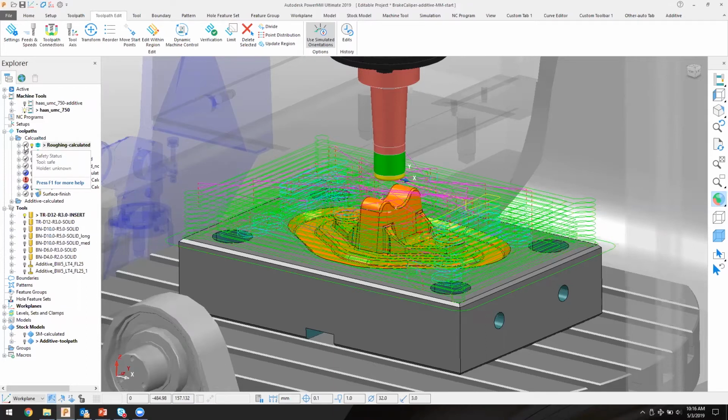So in this case, if I loiter for a moment, you will see the flyout is telling me that the tool is safe, but the holder has not been checked. Now, if I move down to this blue checkbox, you can see that the tool is safe and the holder has been checked as well. And the red exclamation point, I forced it to do a little boo-boo, and it gives you that red exclamation point that tells you, hey, you need to address this and have a look to make sure that you're not going to ruin anything on your machine or tooling.